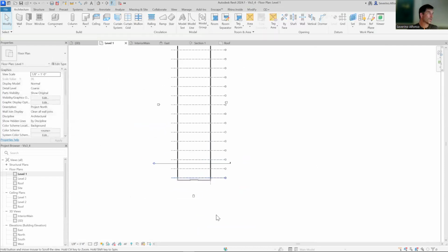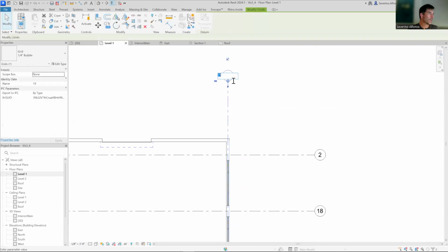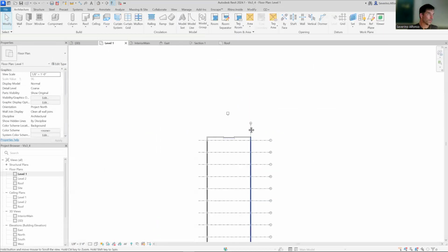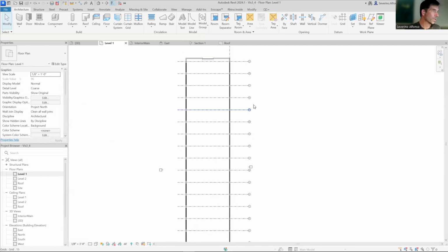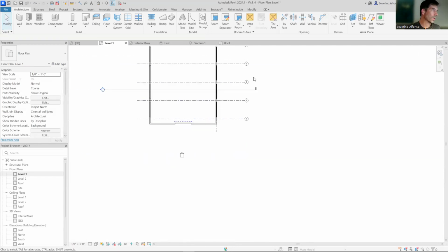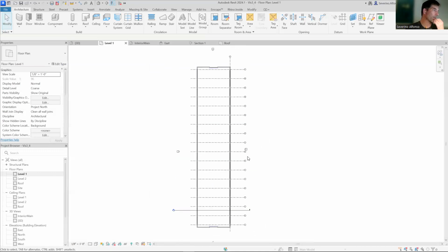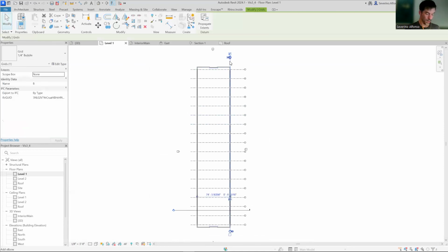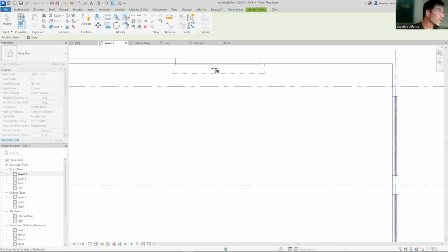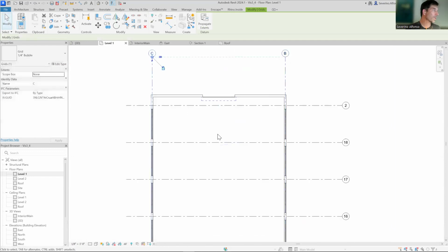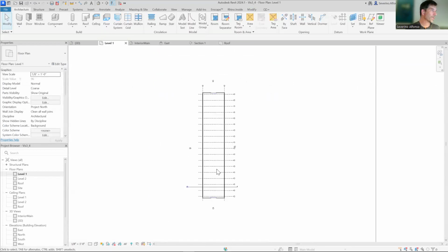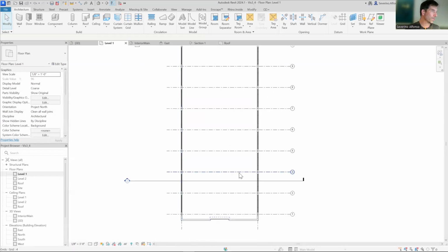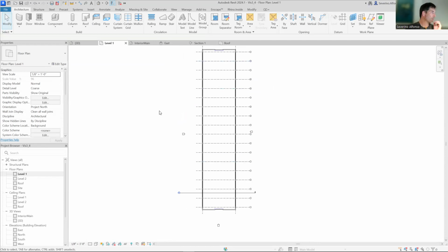There you go. And I'm going to name that, because typically the vertical grids have a different numbering condition. By the way, you will have 1, 2, 3, not 1, 3. It will be in that particular order. And I'm going to select that one and do a zero DM and use the middle point here. Okay, so that's that. We're going to be placing trusses, from the third on to the last ones.